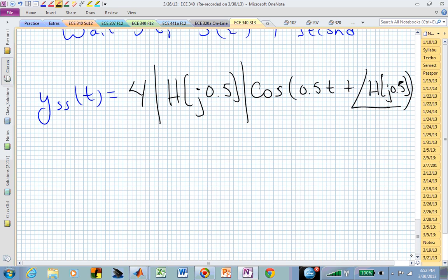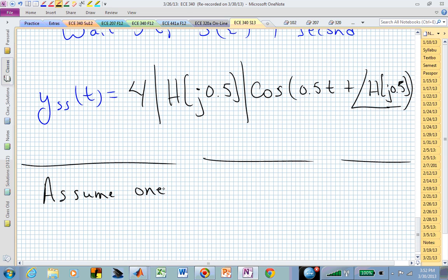Let's now look at the case where we just look at one pole factor. That previous example looked at a 1 zero and 2 poles, and maybe it wasn't clear what the poles were actually doing or how they contributed to the behavior of that output response. Let's now assume one pole at a value of frequency s naught of -a plus j omega naught.